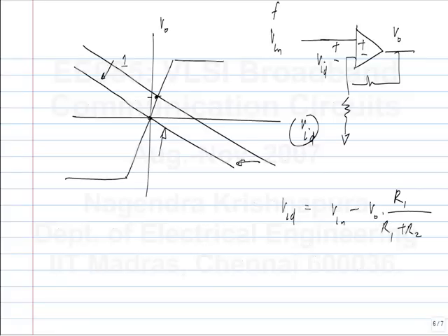Okay. So, the bottom line is when we have a linear combination, that is a number of quantities being summed together, the mean square error of the output can be minimized by updating the coefficients in a certain way. And in this particular case, the gradient turns out to be in a relatively simple form. That is, you have the error and you have the input to that coefficient, you multiply the two and that gives you the update for the coefficient. You have to scale it by some value mu so that the update is small enough so that convergence is guaranteed. Okay, that's the bottom line.